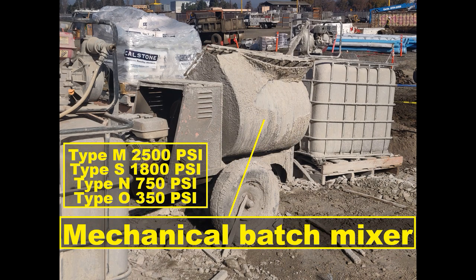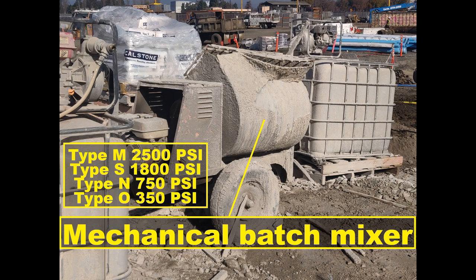Mortar mix. Provide mortar type S, N, O, or M, as specified otherwise herein. Do not use masonry cement in the mortar. Do not use air entrainment in the mortar. Use ASTM C270 Type S cement lime mortar for seismic force resisting elements indicated. Type M mortar mix has the highest amount of Portland cement and is recommended for heavy loads.